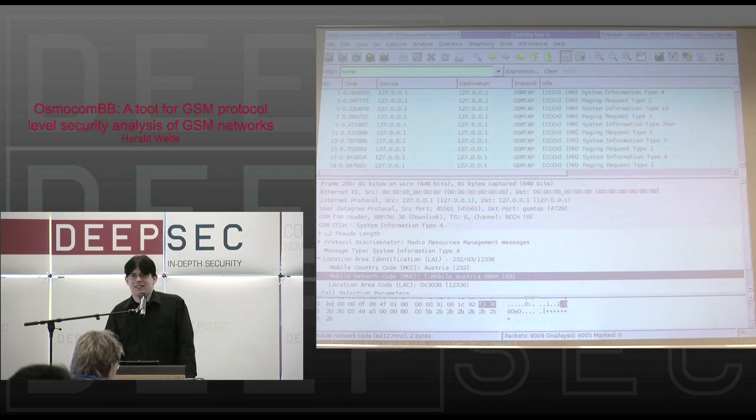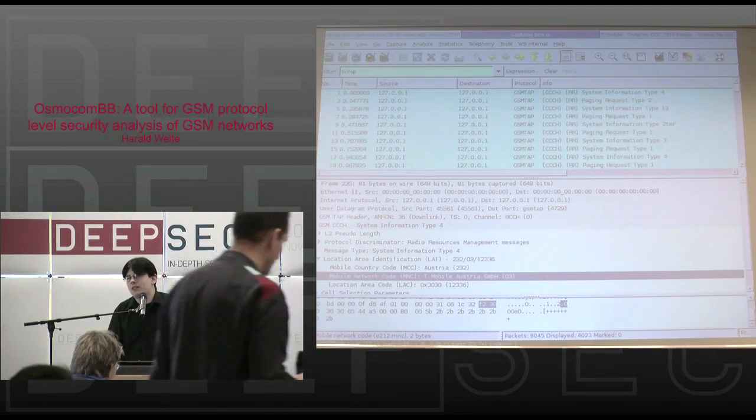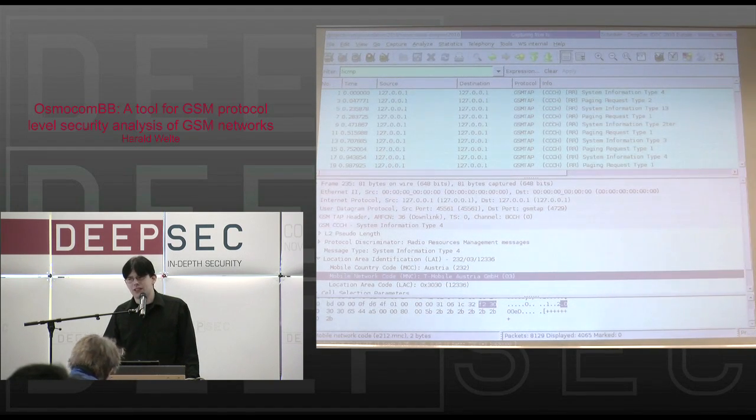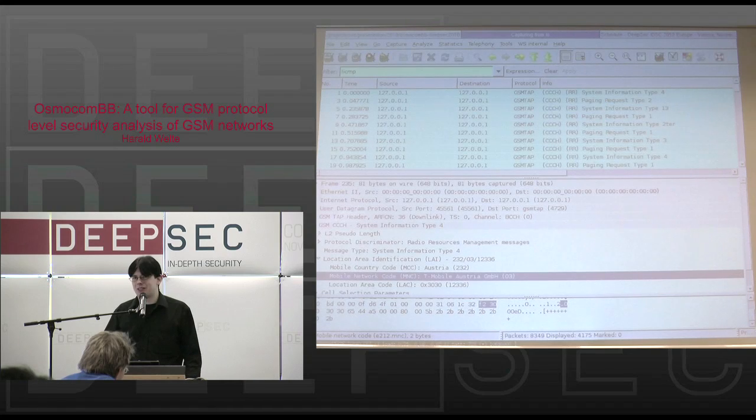Yeah, well, 3G, the problem is that the chipsets are much more, so first of all, the technology is incredibly more complex. So 3G networks, you know, if you think GSM is complex, 3G networks are much more complex. The layer 2 with GSM is extremely simple. The layer 2 of WCDMA is already this ASN.1 specified monster that uses packed encoding rules and has SDL specified state diagrams and God knows what. So the complexity is bigger. I'm not saying it cannot be done.